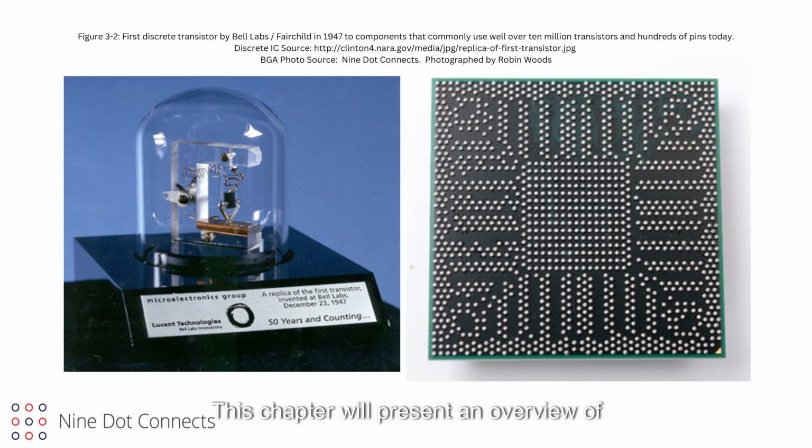This chapter will present an overview of some of the latest assembly processes. It will mainly discuss SMT, surface mount technology, processes, but will include a few through-hole comments along the way. Throughout this chapter, we will use the terms SMT and SMD, surface mount device, interchangeably. SMT refers to the technology used to mount the device, whereas SMD refers to the device itself.